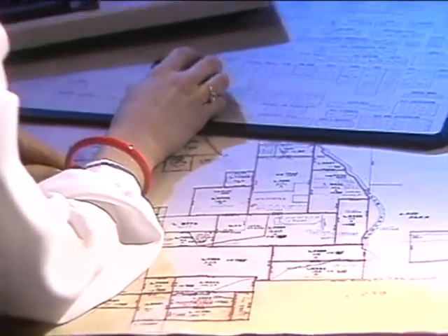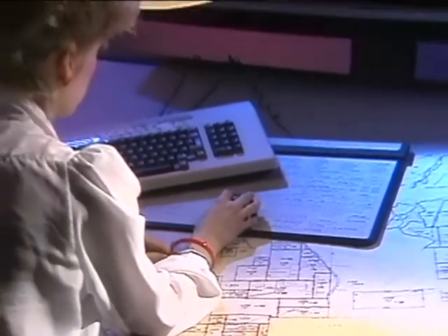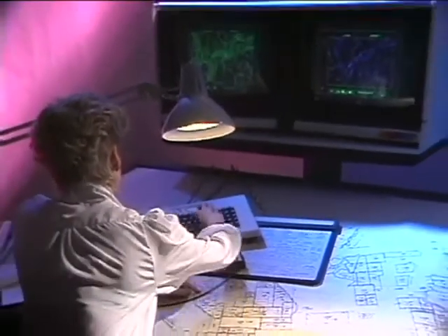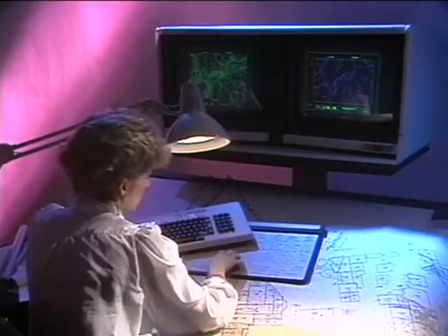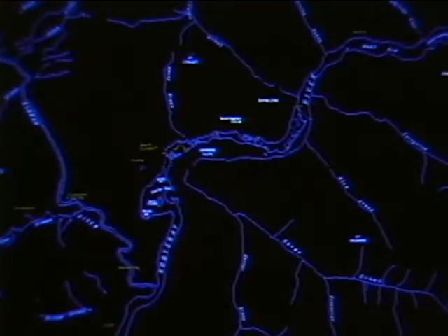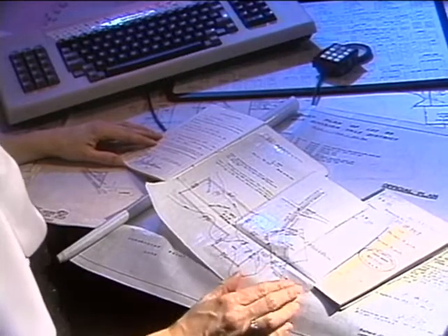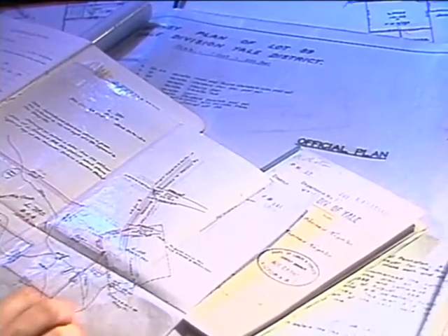When the Ministry of Forests and Lands map-making operator starts work on constructing the cadastral level of a map sheet, she will start with a planimetric base map, usually in digital form. The base map illustrates visible, natural, and man-made features related to the Earth's surface by survey control monuments. The operator begins by entering the survey control monuments. She will then look at the original cadastral survey documents, including right-of-way plans, subdivisions, retracement surveys, and original field notes to determine which plans relate to the existing survey control.